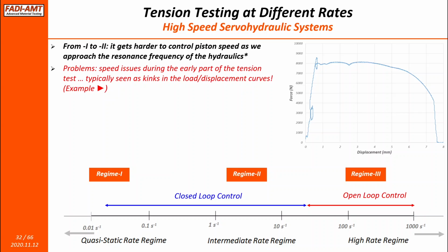So I call it, to me, it's the ringing in the intermediate range, because it's somewhat like ringing at high speeds. It's just caused by a totally different resonance. It's not really the load train resonance, it's the hydraulic resonance.